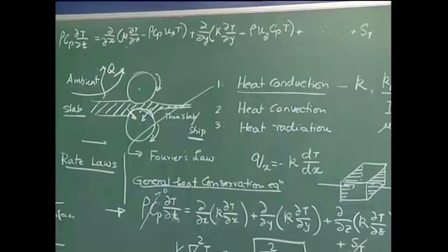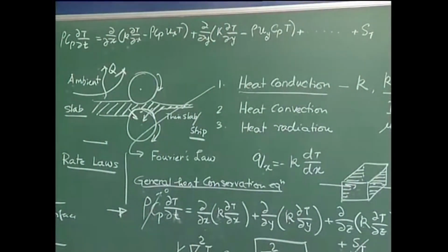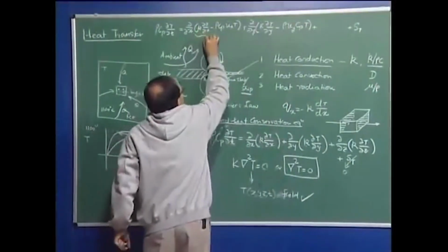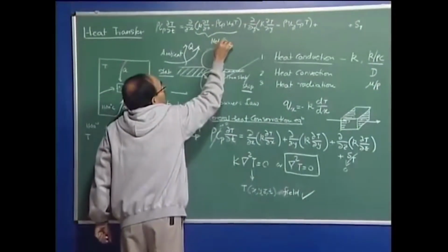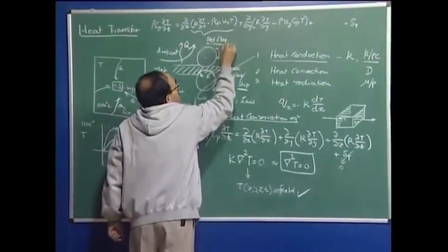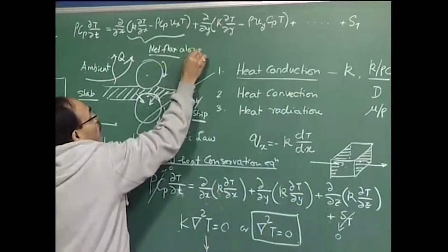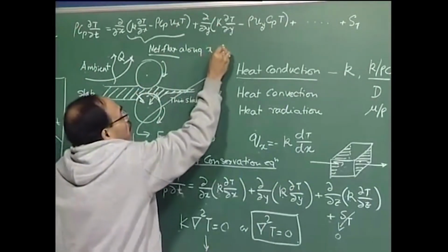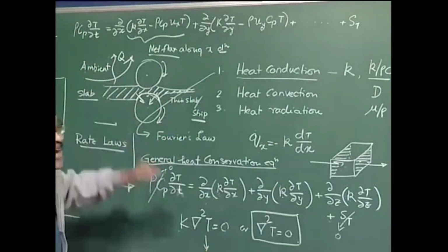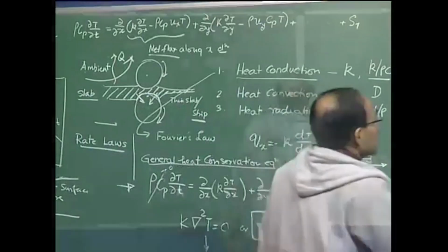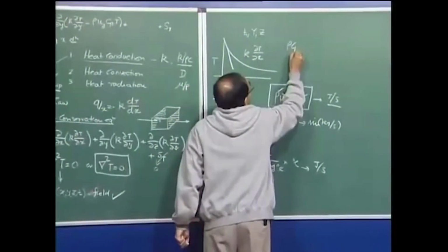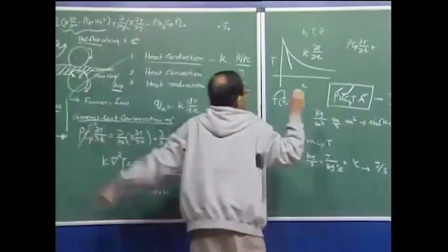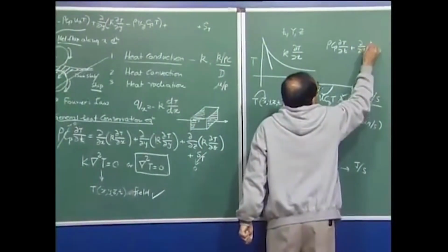the volumetric heat source term. So, this equation is typically also written in this particular form. This is one way of writing, where this is the net flux, and net flux, as I have mentioned, is the net flux along the x direction, because unless you specify the direction, flux has really no meaning. So, finally, I can write this equation in this particular form: rho Cp del T. I bring these negative terms to the left hand side, and then it is like this.